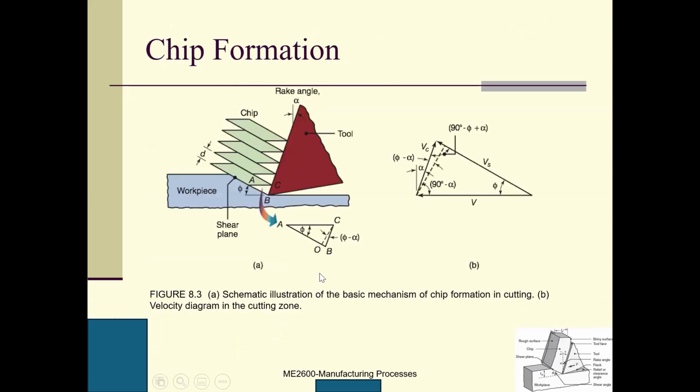of velocity. And then this one, chip formation, and we use the sine function that we have learned in trigonometry to relate the cutting speed V, along with the chip speed Vc, and Vs is the shearing speed on the shear plane. Here's the gamma. We also have a gamma. Gamma is the shear strain along this shear plane. So please write this down.